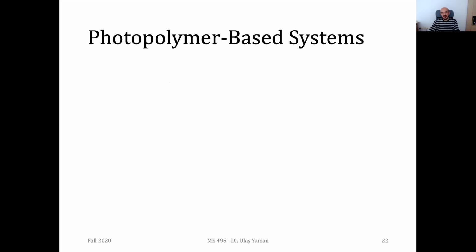For the polymer-based systems, we are using liquid photopolymers first, and then with the help of a laser or light sources, we cure and try to solidify the parts. Here's an example, for instance, a bunny. This is fabricated by using SLA technology, a technology using photopolymers.